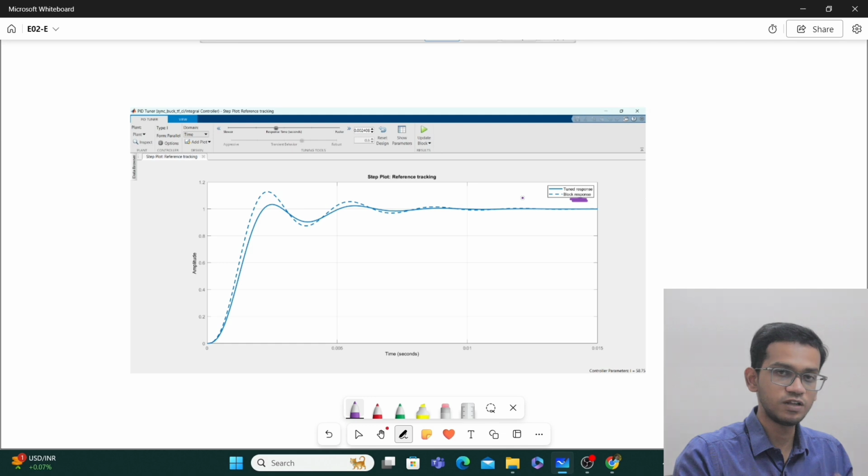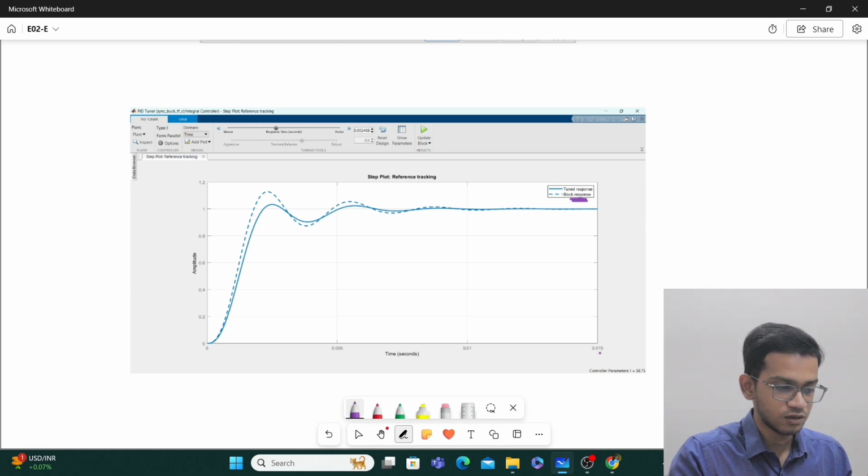If that is a requirement, then you will make sure that that requirement is satisfied here. If my requirement states that my settling time should be less than 50 milliseconds, then it is satisfied here because it is only 15 milliseconds.